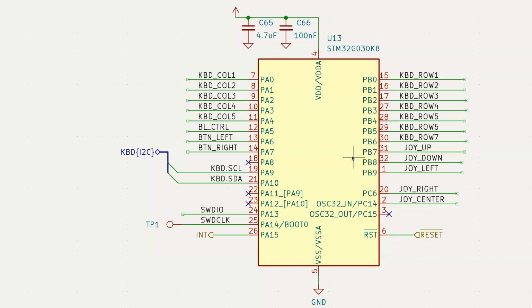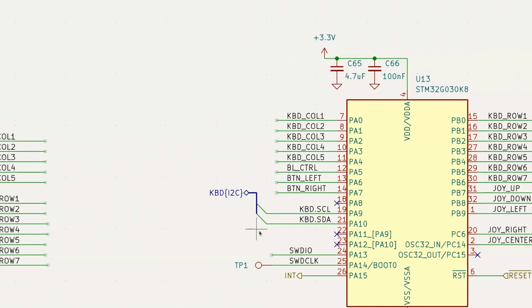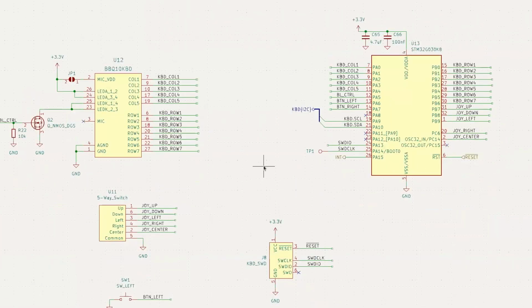When it is pressed, it queues a key press in a buffer that can then later be read over I2C. So it takes something like 20 GPIO and condenses it down to just 2 wires on an I2C bus that can be read. And it allows you to push multiple keys at the same time, so I can mash a bunch of buttons and know exactly which buttons I pushed. That's kind of the trick of matrices.